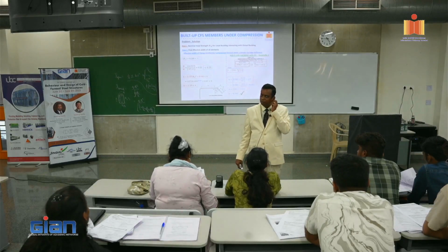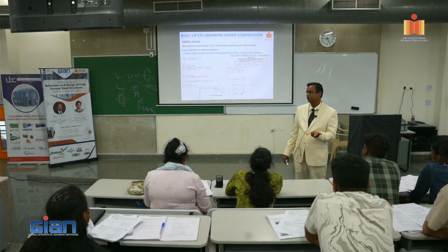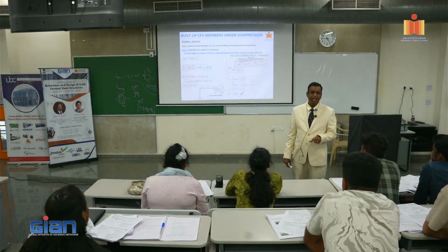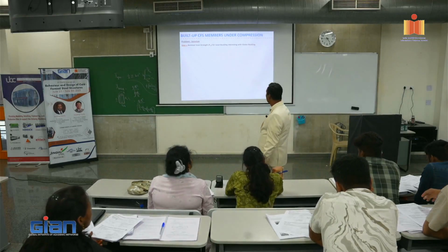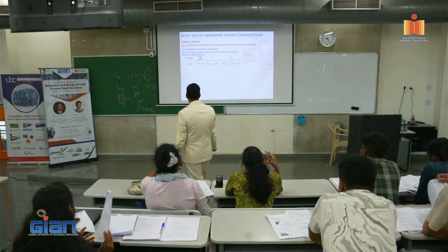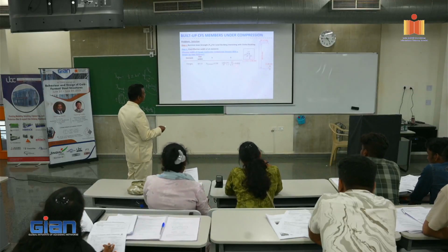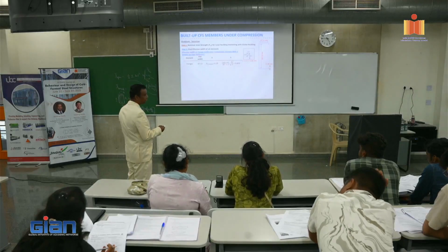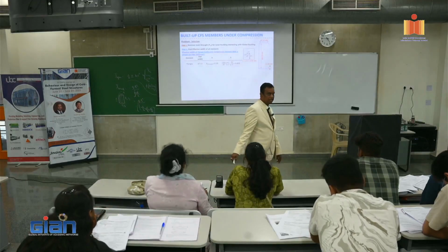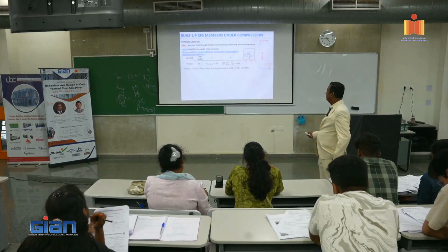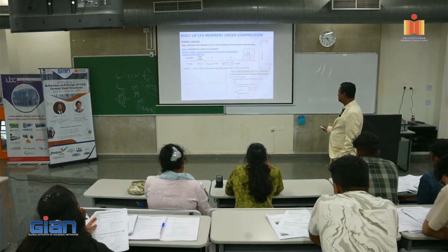No. Slenderness of the member. Because that lambda sub C tells you the slenderness. Based on the slenderness, I have to determine which equation I should use. Right? So that's why I have to find out this. So now, this is 2.29. So I can find out the slenderness is 0.853. Everything is known except K, you put 2.29, right, you get 0.853, which is your lambda, slenderness ratio, right?